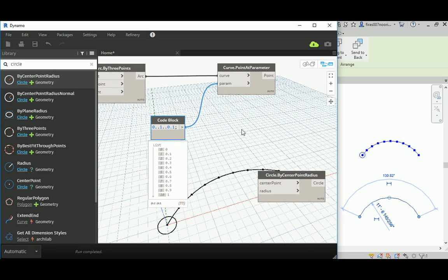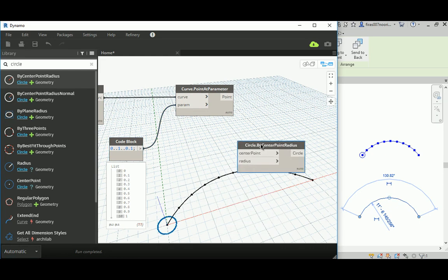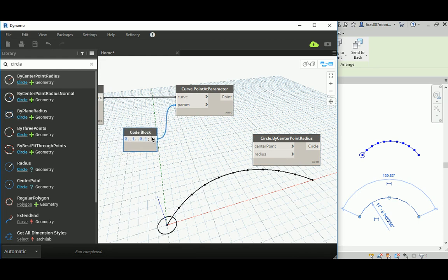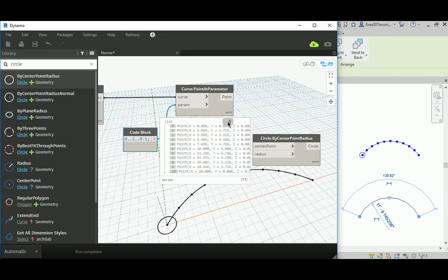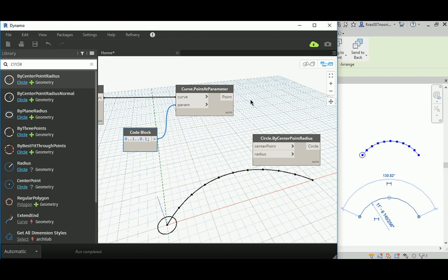Now again, the fight in your brain goes less and less, because if I can do that in Dynamo without the pane in Revit, I cannot divide that easily. Maybe you can do that in AutoCAD, yes, but it is not that easy to do inside Revit. Now you spend a couple of clicks and it gets you the result. Again, if you hover over the output, you can pin that and you see the points being generated if you want. If you don't want, just remove your hand and you don't see this big list.